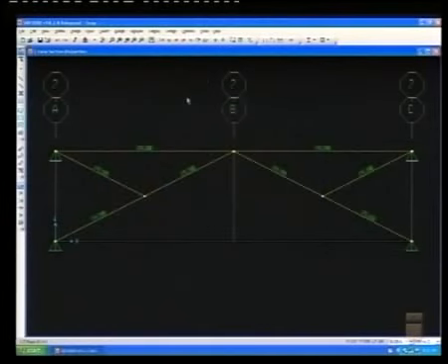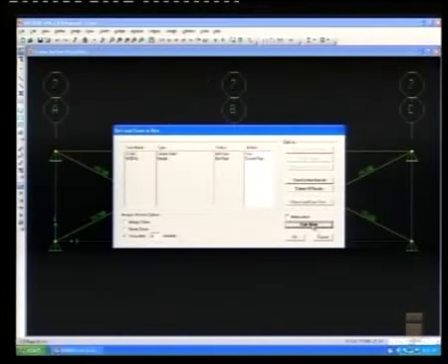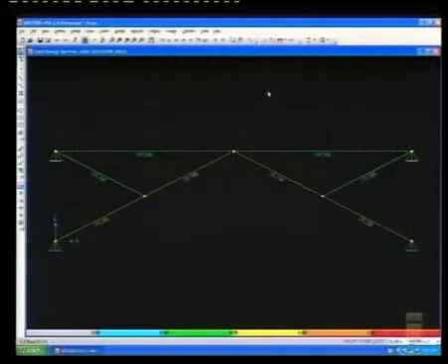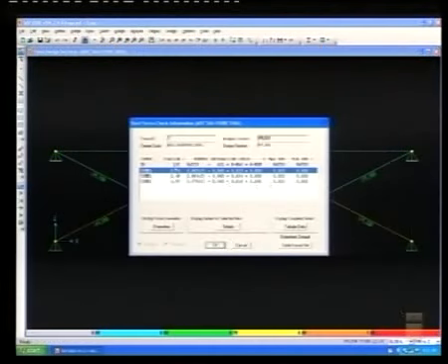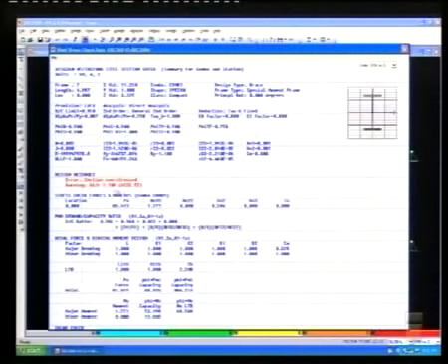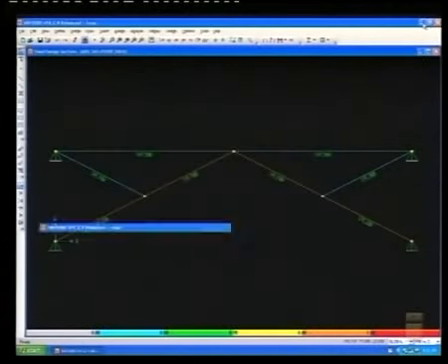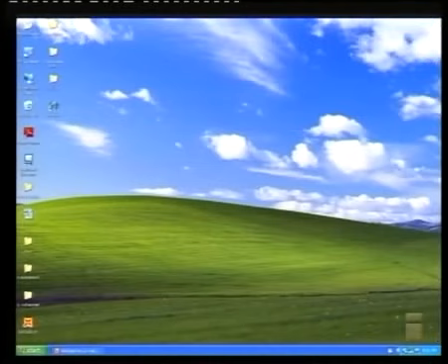Okay. And here, if we analyze it, and then design it, you find that none of the members are in the red zone. IPE is approximately, you got 0.983, so it is less than 1. SAP, if it is more than 0.95, will give us a section that is overstressed. Now, it is an IPE 200. You did design it. You don't want to do verification, or you wanted to do just 2 types of verification.